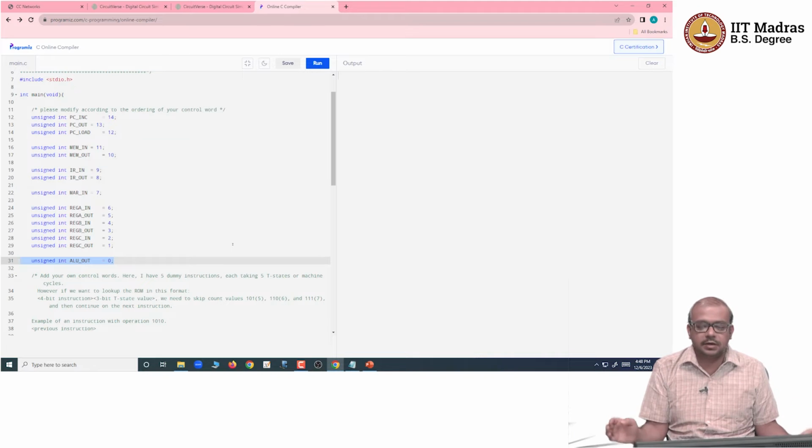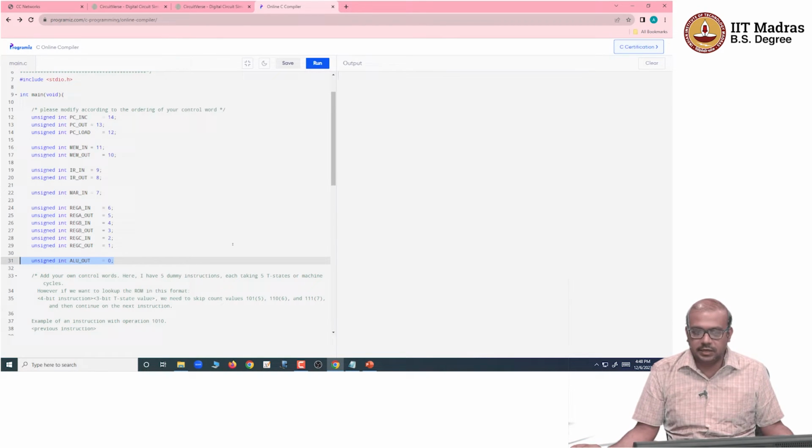That's a separate discussion. In the control logic, we do not have anything like that, because we are not choosing any registers to be connected to the ALU for the inputs. It is always A and B. So for any computation to take place in the combinational circuit that the ALU has, you have to make sure that A and B are loaded with appropriate values that you want to make your computation on, right?